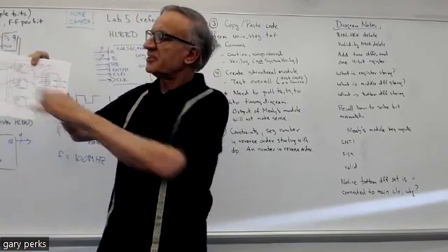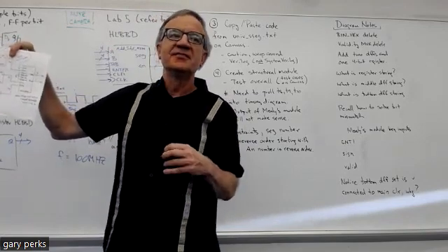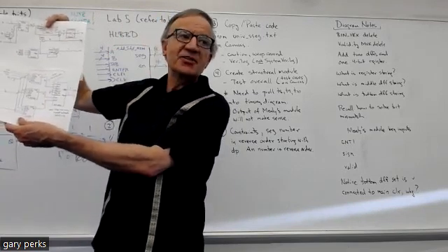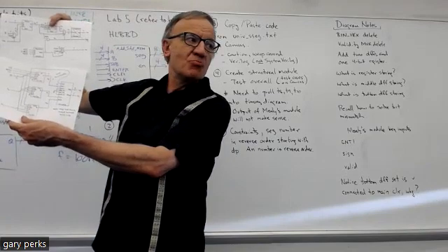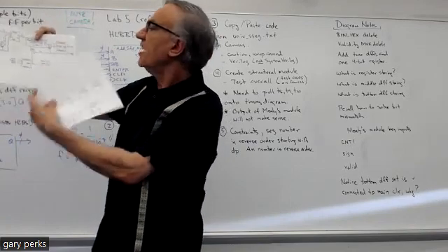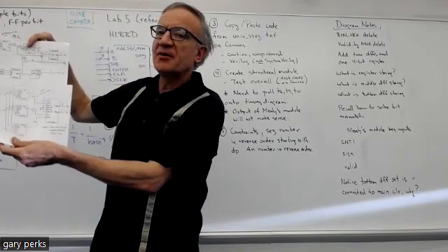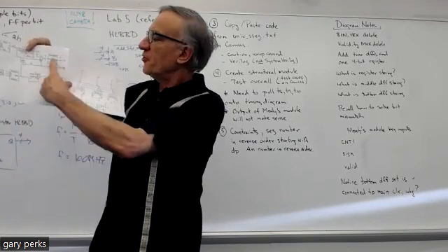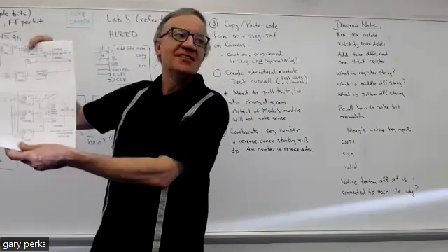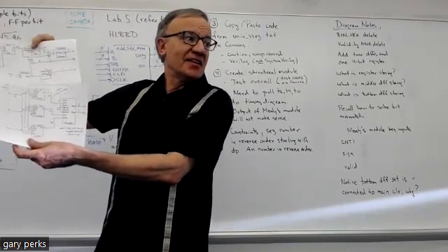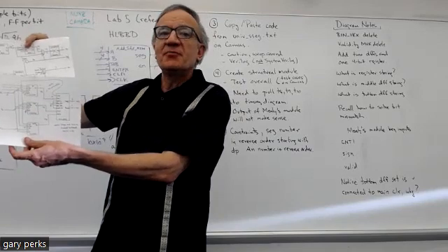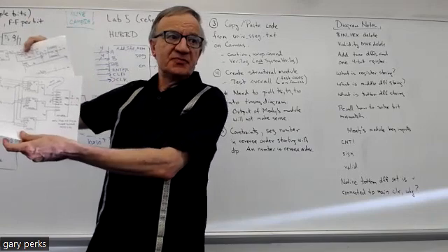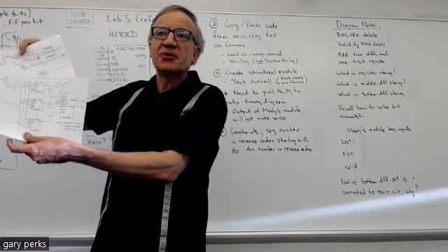Where does its D input go? T5, the output of this MUX. What data is at the output of that MUX that used to go to the decoder you deleted? That's the binary number, the 4-bit result. So that top register is storing the result of either your addition or subtraction.